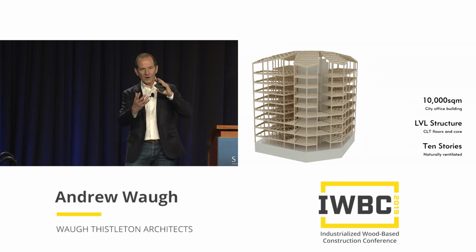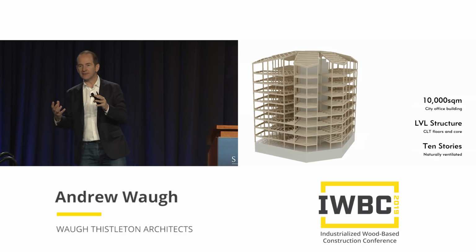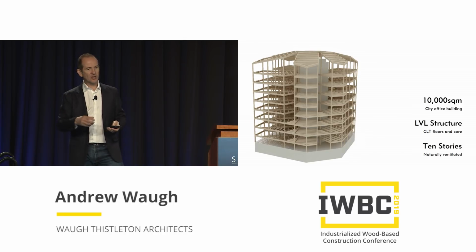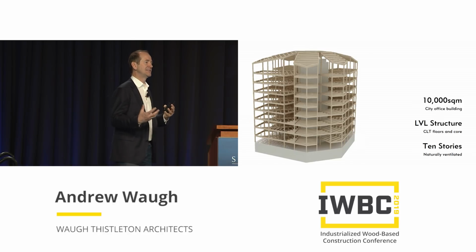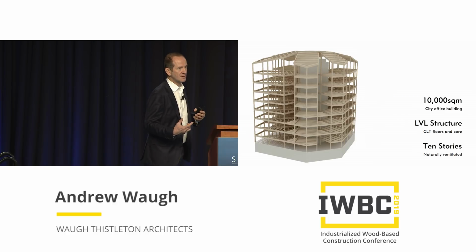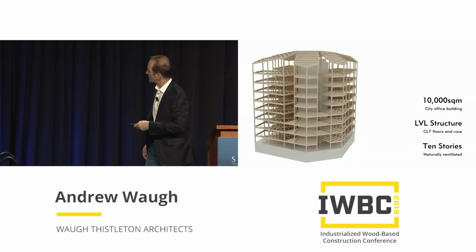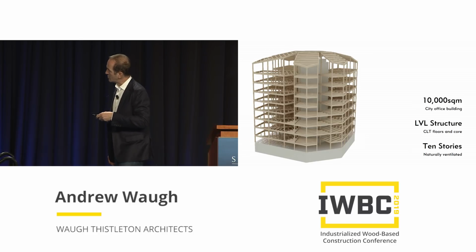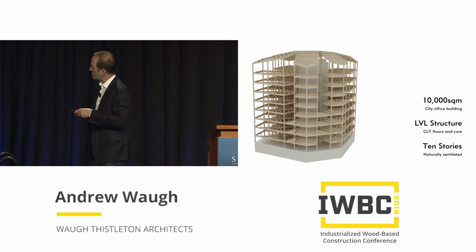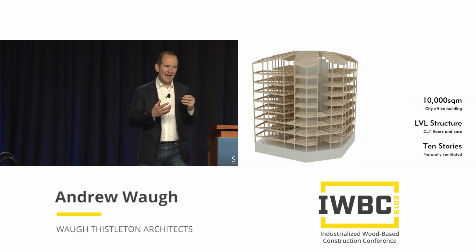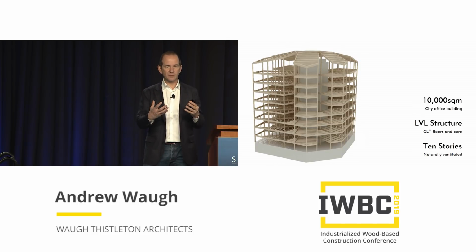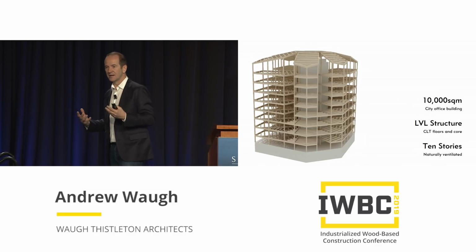And what we're able to do, because we don't have any concrete in this building, is we don't have any concrete that we need to cool down, and we don't have any concrete that we need to heat up. So in effect, this building is very easy to heat and very easy to cool, because we can naturally ventilate the whole building. We have these little slots here in the structure that give us the opportunity to bring fresh air in and bring it round. Because actually, you're not having to heat or cool down the structure of the building. You're just having to change the air. You understand?